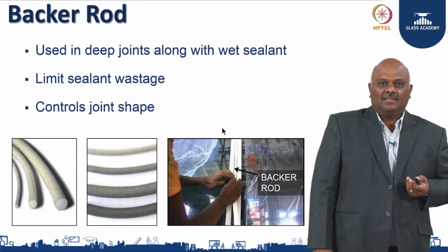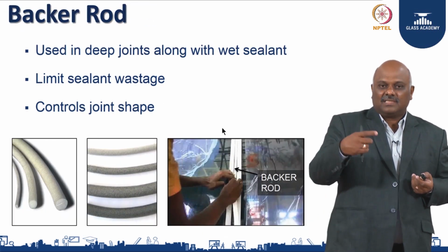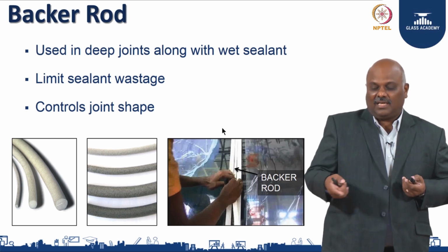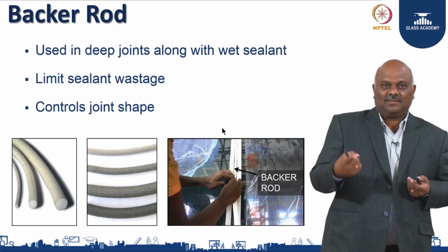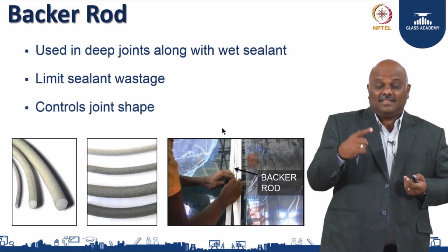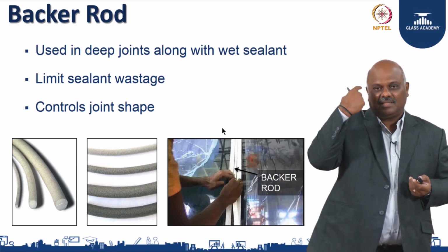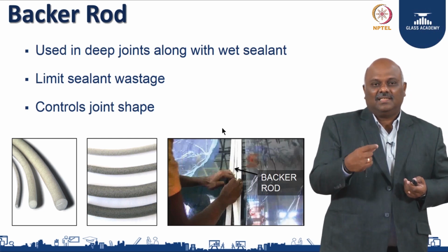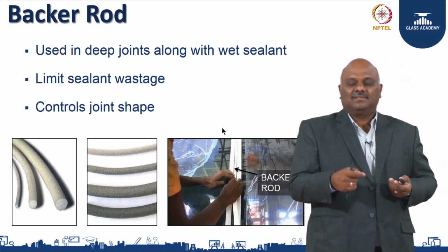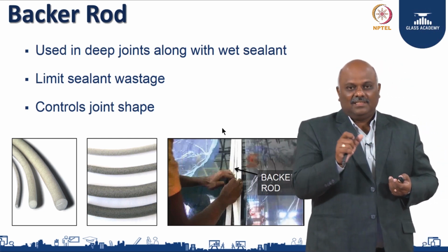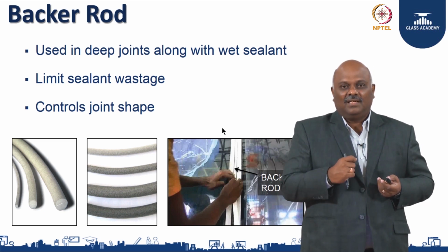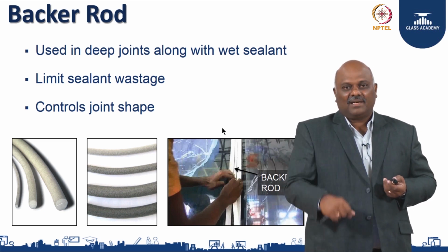Backer rod. Again, when you start doing any sealant work, you can't just simply press sealant. It is not viable commercially, plus it will not work because sealant will take time to cure. So for sealant, again, they have a calculation which will tell you the width and depth ratio. To contain the width and depth, you use a backer rod.